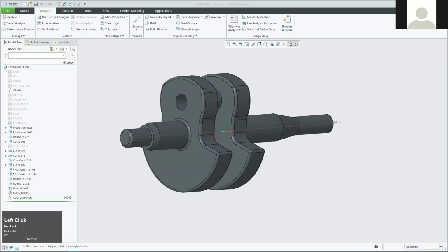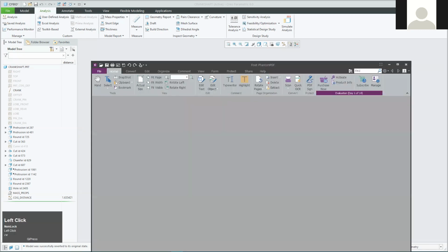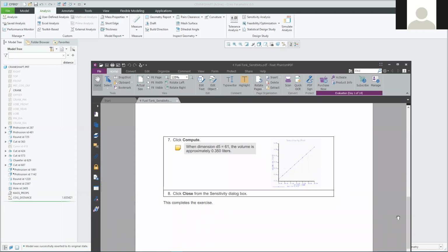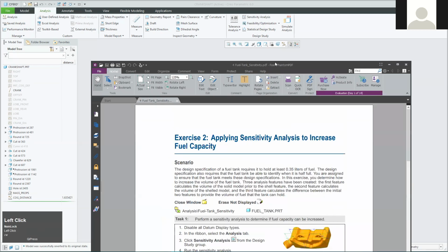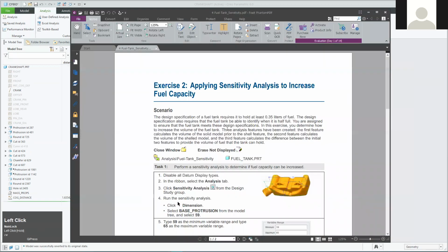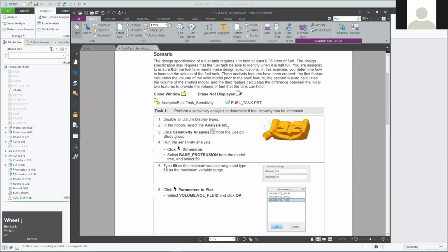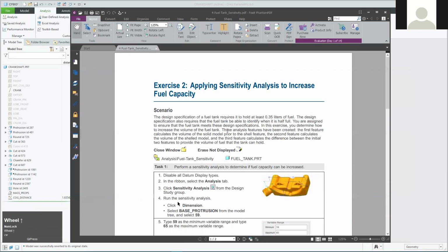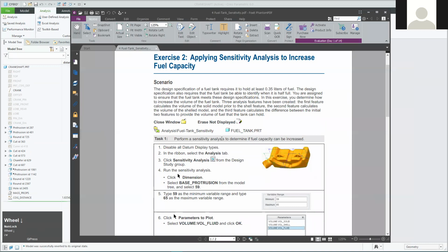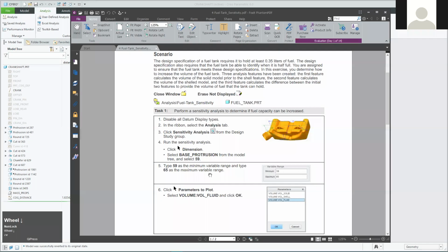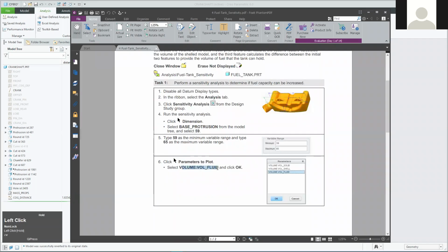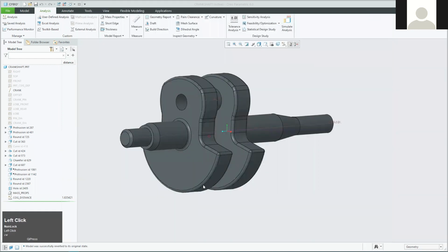But essentially, the BMX acronym in this case is Behavioral Modeling Extension, which is a plugin for Creo, the plugin that you don't get with the student version, but you do get with the university versions. So when it talks about BMX features, it's behavioral modeling extension features. And that covers all these volume monitoring features that we've created, all the distance monitoring features, all the mass properties features, and all their parameters that you can also store within them.